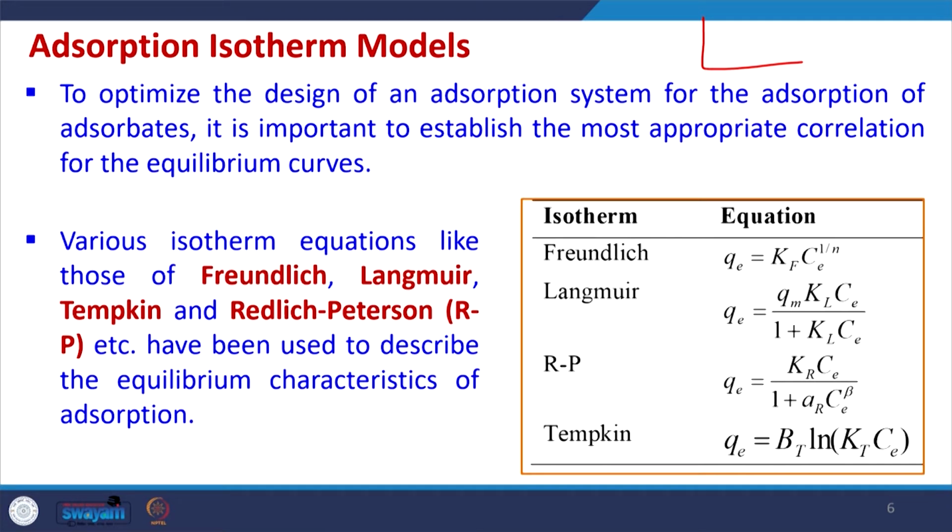So, like for Henry's law. As per Henry's law, the equilibrium data is generally linear because we consider only dilute concentration. If higher concentration is there, the curve may be like this. So, the operating line may be like this. We can decide the operating line ourselves, and based upon that we can find out the length, height, diameter etc. of the actual packed bed.